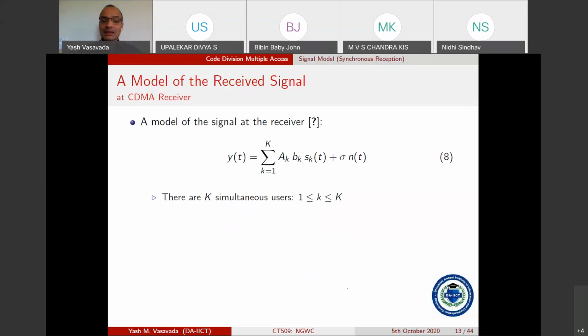And so TDMA is an example of what is known as orthogonal multiple access. Similarly, FDMA. In FDMA, different users take different frequency bands. And it can be shown that the signals that are occupying two non-overlapping portions of the frequency axis are again orthogonal to each other. In the vectorial sense, you can picture them as forming 90-degree angles.